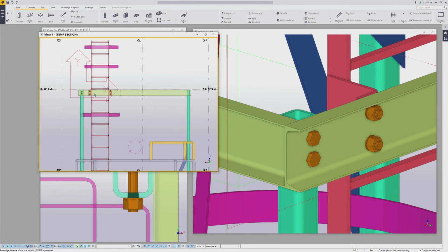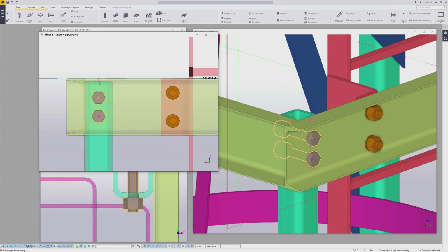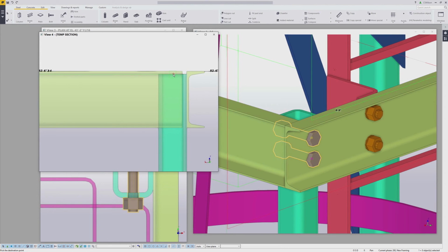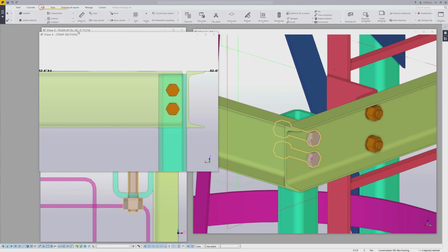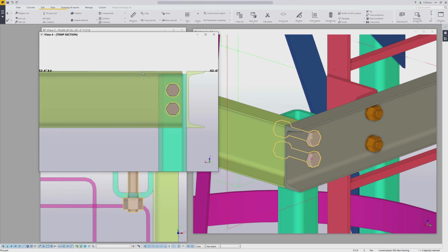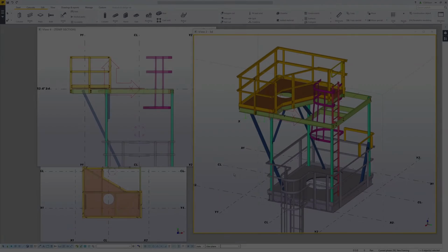Now I can come to the other end, select my bolts, right mouse click, copy, and we can give the top point of this column over to top point of that column. And to verify that everything is okay, we can go to Edit, Measure, Bolt Spacing. We can select these bolts in this channel. We can see we're 1 inch away, we're 2, 2, and 2, so we should be fine.